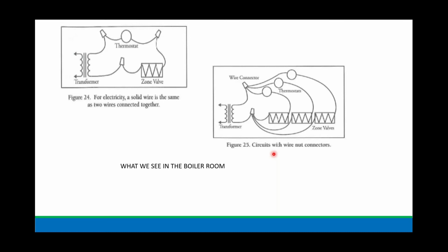So you want to make sure that when you are wiring up a system, or maybe if you have a system that's having problems, check and see that you've got the right wire nut, or the right wire nut was used, because you may not just have a good connection. And once you do twist that wire nut on and make a good connection, you want to tape it off so even if somebody tugs on the wire by accident, it doesn't pull it out of the wire nut.